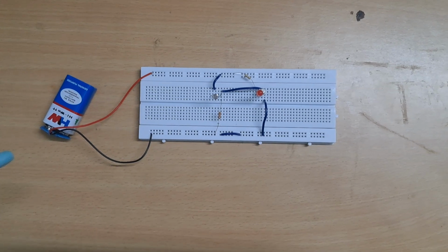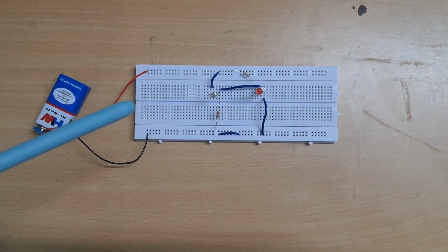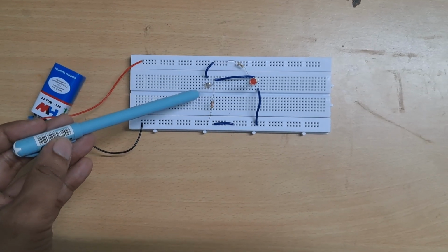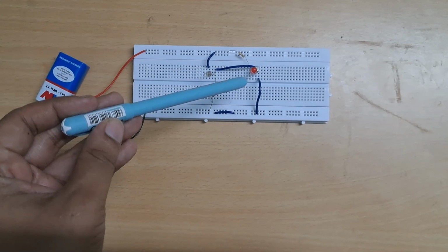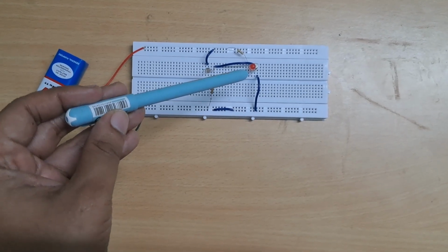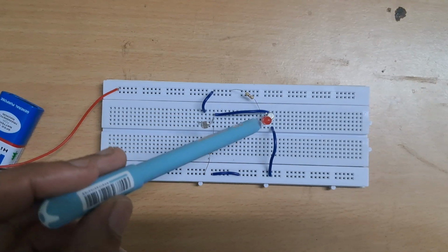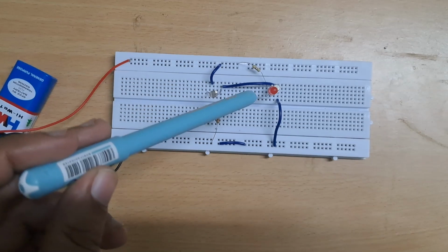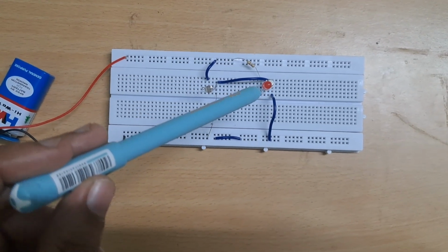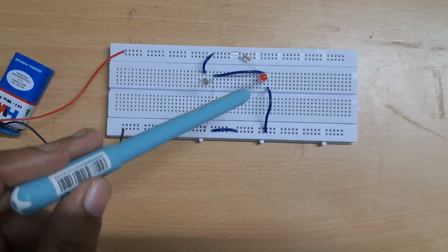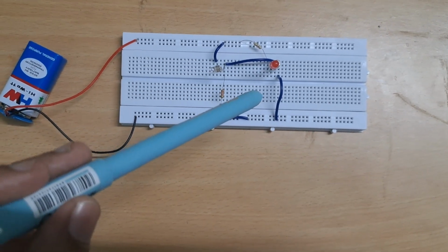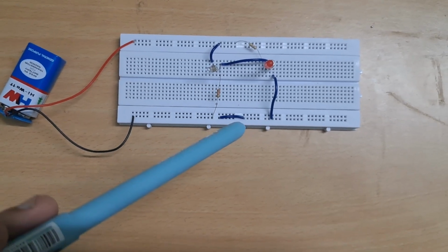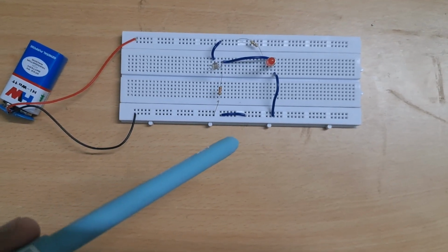So here we have connected a 9-volt battery as a power supply. This is the LDR component, and then we have also connected a red colored LED. Behind the LED you see a 2907 transistor, which is actually performing the switching action. It is a PNP transistor. We are using PNP here because we want to switch on the light when it is dark. So for that purpose we are using a PNP transistor.